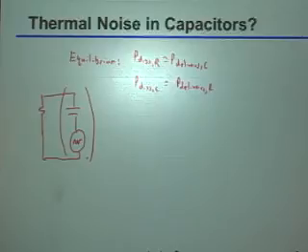What do you guys think? If I put voltage across the resistor, does it dissipate energy or not? Yeah, it does. The resistor would perfectly happily take whatever energy is coming out of the capacitor and dissipate it. So in other words, voltage noise appears on the resistor, and the resistor dissipates that energy.